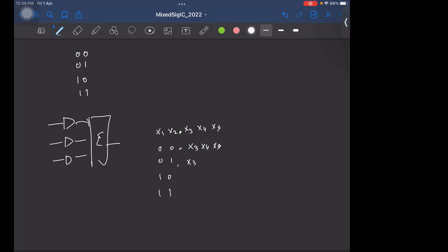Okay. So again, you can think of this as some kind of redundancy. You are having redundant bits in the output so that you can correct for any errors you are making in the DAC design here. Is that okay? And of course, this is not the only way in which you can correct for the DAC errors. There are other ways also, but this is one common way.